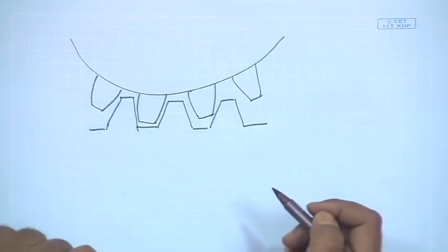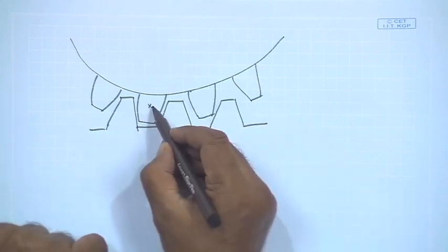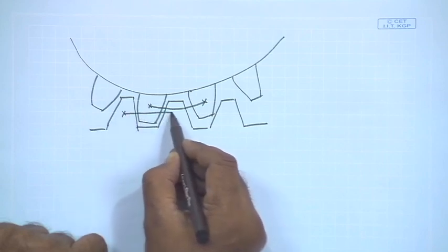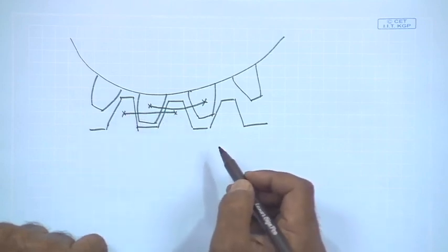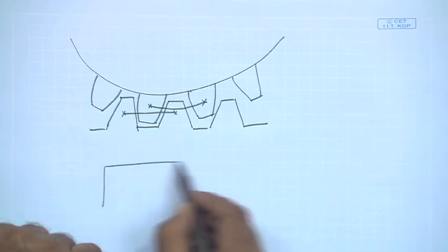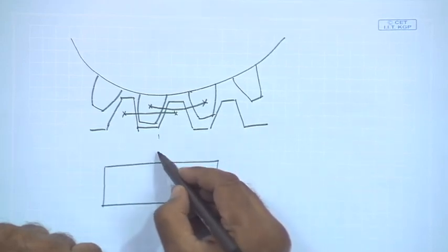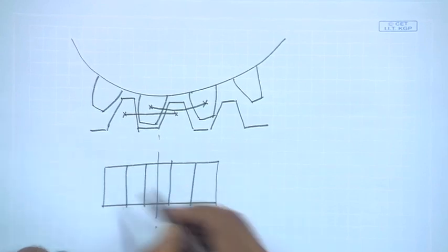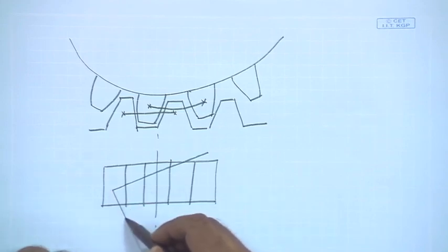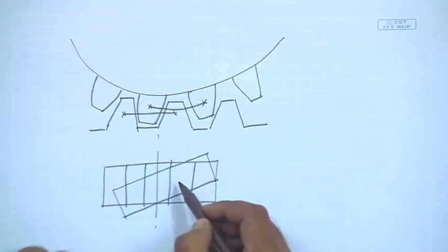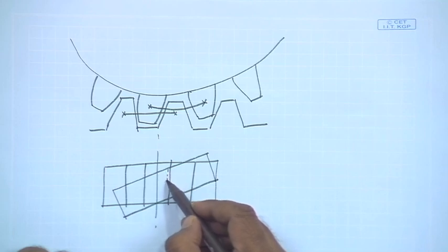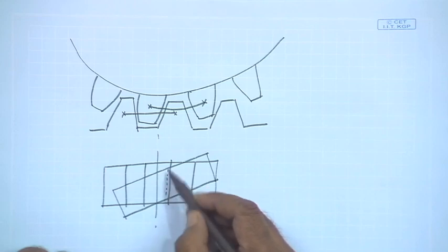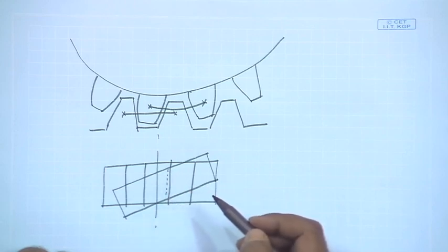This sort of a relation is existing, which means the circular pitch is equal to the linear pitch, but if you remember in the other view, the worm gear being like this being a spur gear, the teeth are of this type and the hob has to be at an angle so that its thread matches in direction, in alignment with the teeth of the gear.